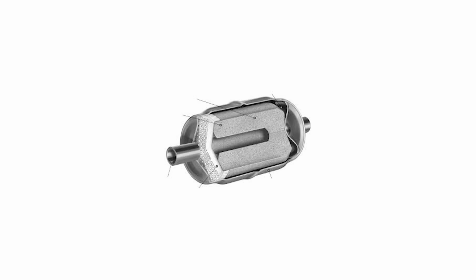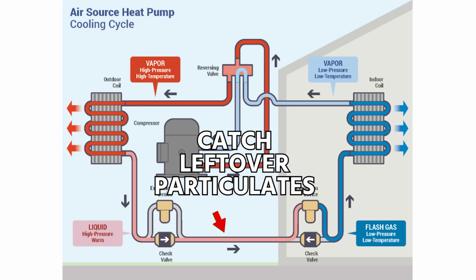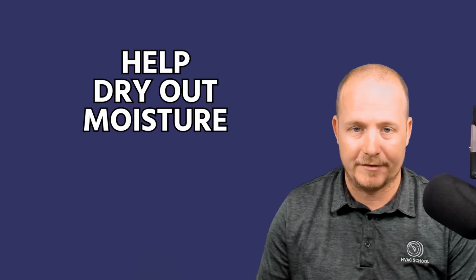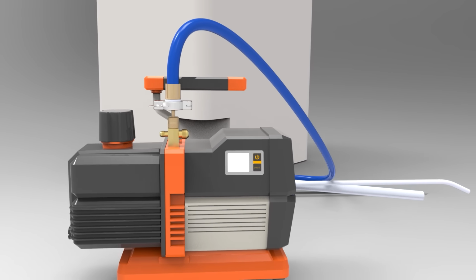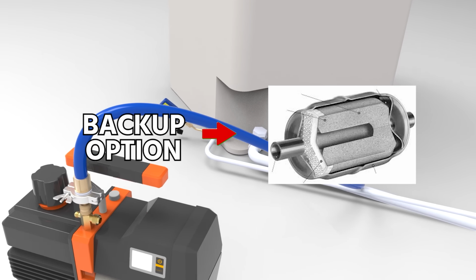The liquid line filter dryer goes in the liquid line, and its job is to catch any particulates that may be left in the lines or in the system or may be generated within the compressor over time with wear, and it's also there to help dry out any moisture that was left in the system. Now, you shouldn't have any significant moisture in the system because you evacuate, you pull a vacuum on the system, and that should remove that moisture, but the liquid line filter dryer is there just as a backup plan.